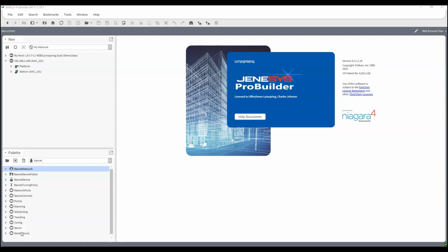Modbus has been around since 1978, and it was created by Modicon. It's royalty free, which is why a lot of industrial applications use it. However, from manufacturer to manufacturer, it's not very consistent. So when you're going to be doing any kind of Modbus integration, I feel that it's really important to call the manufacturer, get the proper documentation, and ask the questions that you need to ask.